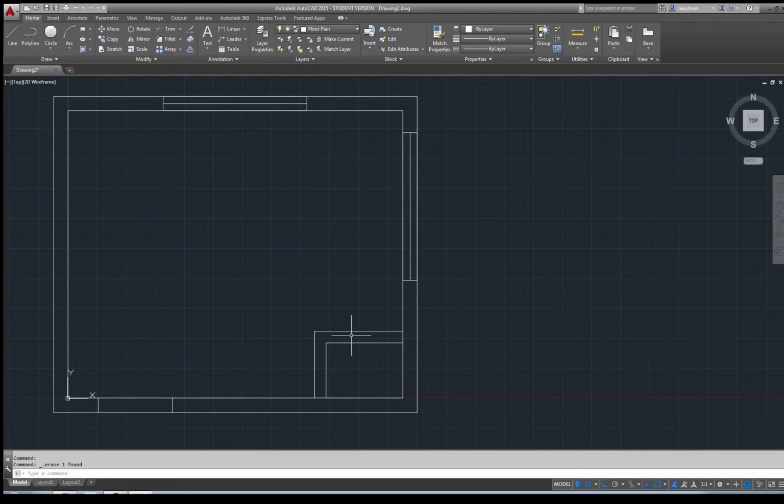What's the advantage? You can turn on and off the interior walls, and you can even delete them or move them around while maintaining your exterior walls. Most times when you do a redesign with the exterior walls, you can't do a lot, but you can work a lot with the interior space.